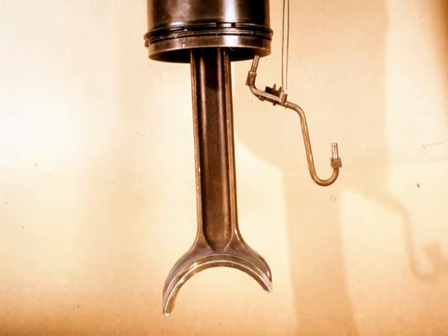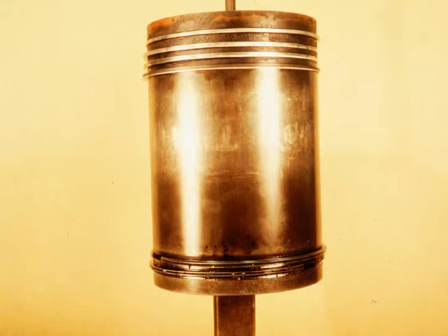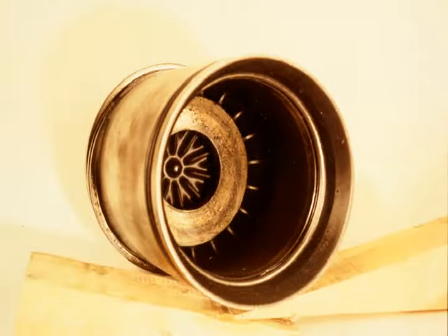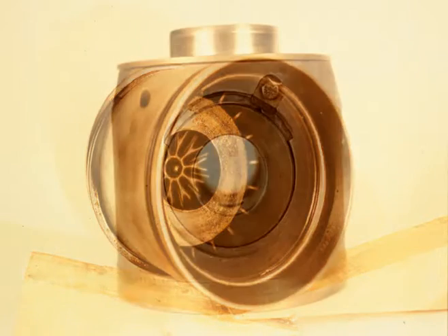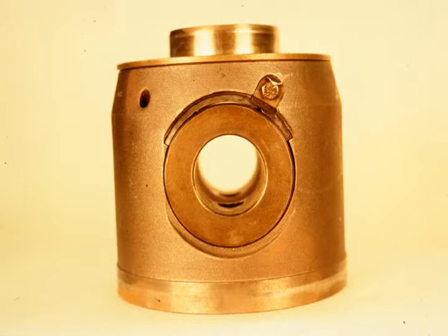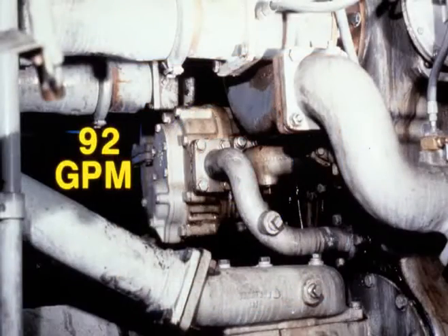Each cylinder has a pipe connected to the manifold that allows some of the oil to be sprayed to the bottom of the piston carrier, to the piston crown, and to the piston ring belt. The carrier allows oil to enter the bottom of the hollow piston crown, where it removes heat from combustion. Some of the oil is used between the piston pin and the carrier bearing to absorb the pressure developed when ignition occurs in the cylinder. At full speed, the piston cooling system circulates approximately 92 gallons of oil per minute.